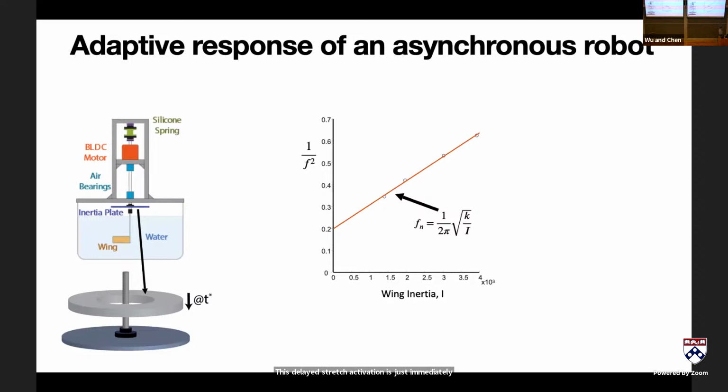This is quite nice because I worked for 3 years trying to make robobees fly, and one of the most painful points is that no two robobees are the same. You build it, and then you need to figure out what the exact frequency to drive it at is. You try to create as sharp a resonant peak as you possibly can. So 110 hertz is different from 111 hertz. And you basically have to figure out exactly what frequency you want to drive that robobee at. This kind of actuation alleviates all that. You just turn it on and it immediately tracks the natural frequency of the system, through setting up the dynamics appropriately so that the system emerges and oscillates at the characteristic frequency of the system.